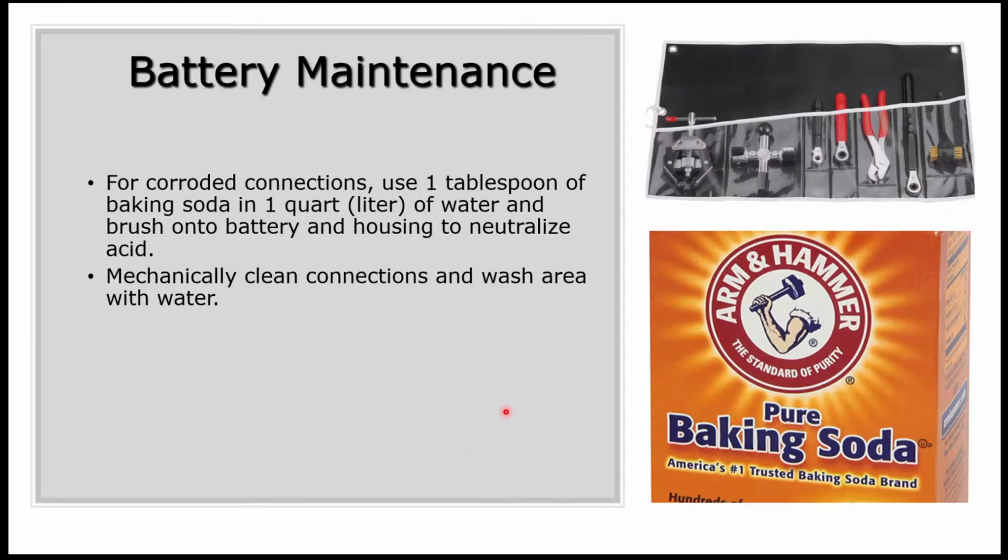If you're pulling on that lead terminal with something like pliers, trying to get the battery cable terminal off of the battery terminal, you could break the battery terminal internally in the battery and break it loose from the plates inside the battery and ruin the battery, okay? That's an extreme case, but you certainly need to be cautious with that, okay?